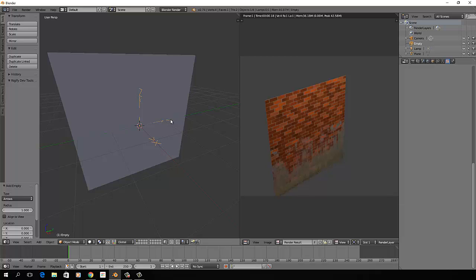By default, Blender will render along the Z-axis, and think of that Z-axis as poking through your texture. As the Z-axis is pointing up, if we render, we can see that our texture decal is rendered just stretched way out of whack. So we need our Z-axis to point out from our brick wall.